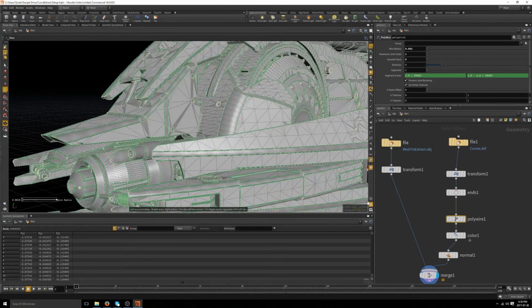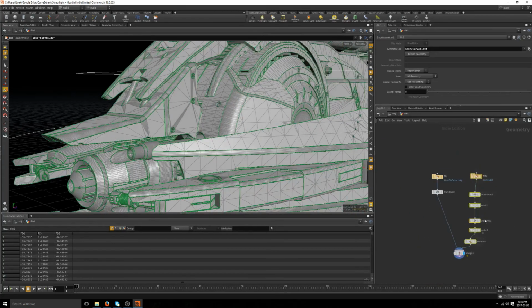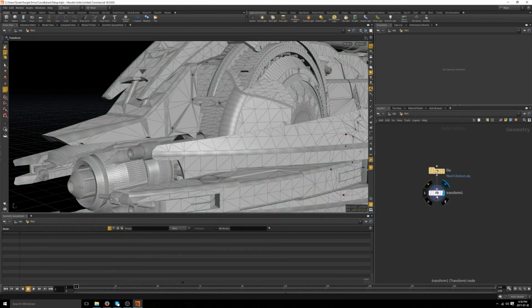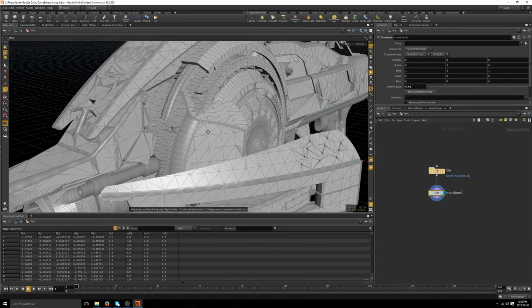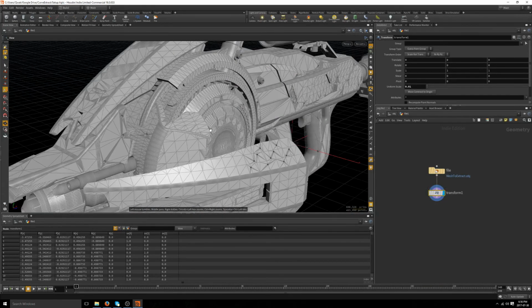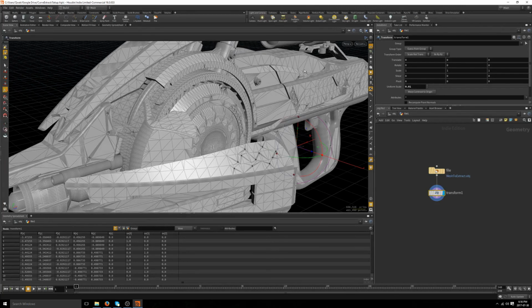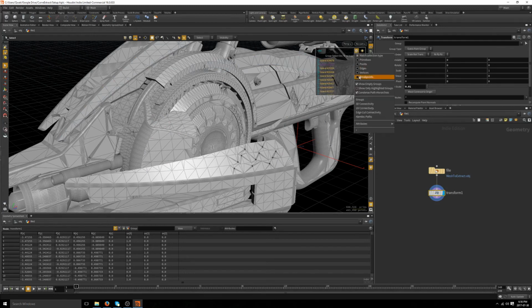So I can just delete all these things and we start with this mesh. As I said previously, what we're gonna do is extract every poly island, because we didn't weld the edges when exporting the models. If I select, yeah, you have to click on this small icon here and select 3D connectivity, and then you can see all the patches, in fact.